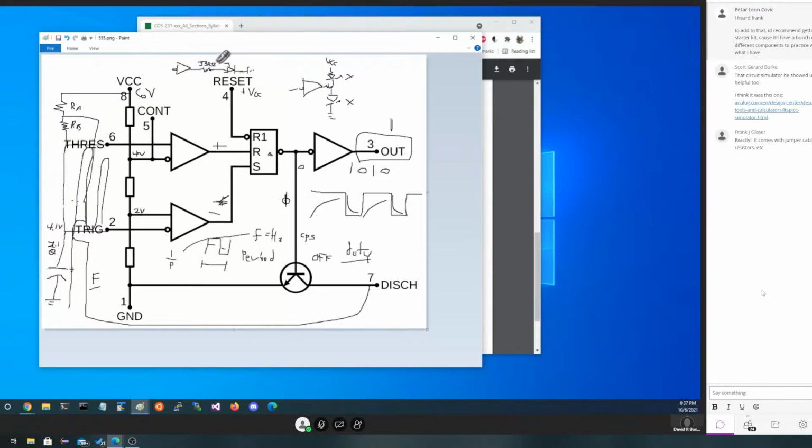Many people will say you need to change the value of the resistor, and that'll certainly work. And as a matter of fact, for the picture we drew here, we didn't say how long the on time was and how long the off time was. All we said is they did this. It was on when it was high, and it was off when it was low. If we make this faster than about 15 times a second, we're never going to see it go out. We're only going to see it being on. But because it's not on 100% of the time, it's not receiving the current it would have been receiving if it had been on the whole time. So what we're doing is something called pulse width modulation, PWM.